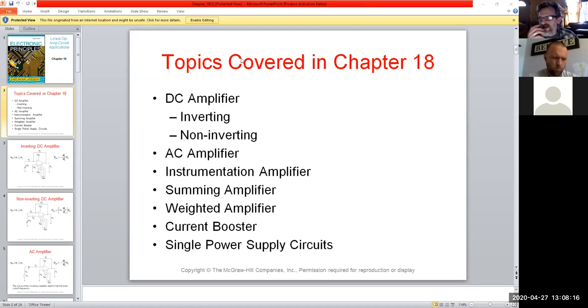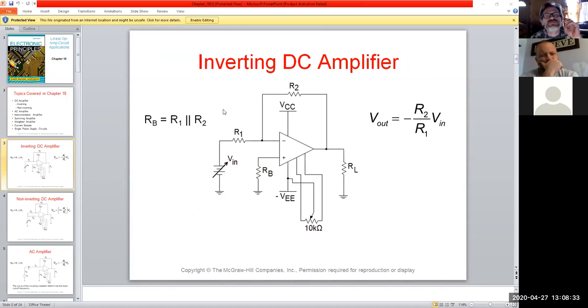Sometimes with some of these devices, especially the transistor drivers, you have to be careful that you don't overdrive, otherwise you'll be pulling too much current and you'll short these things out. They can only handle so much. And then you've got the heat rating as well, where the op-amp one, well, we'll get into that here.